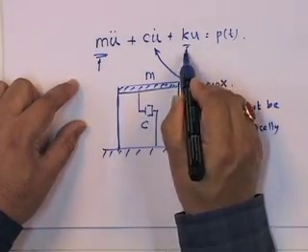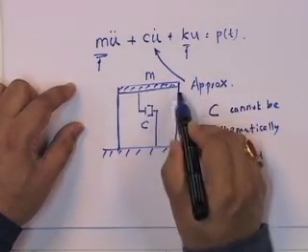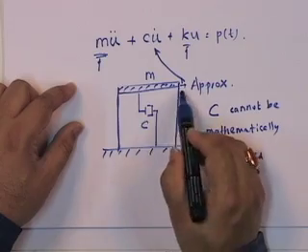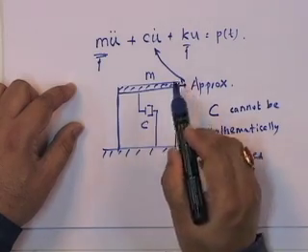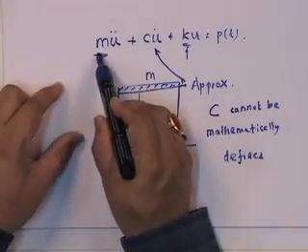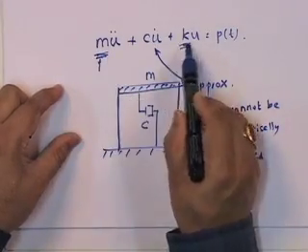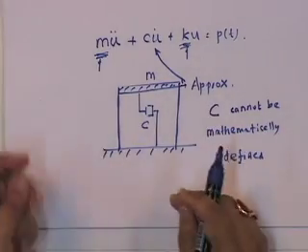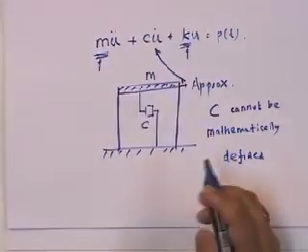K is the stiffness, we can get this. How can we get this? Well, we find out the force that we require to get a unit displacement. So, whatever the force to get a unit displacement, that is the stiffness. So, we can actually measure m, we can measure k in a real structure. We can of course mathematically model it also, m and k.